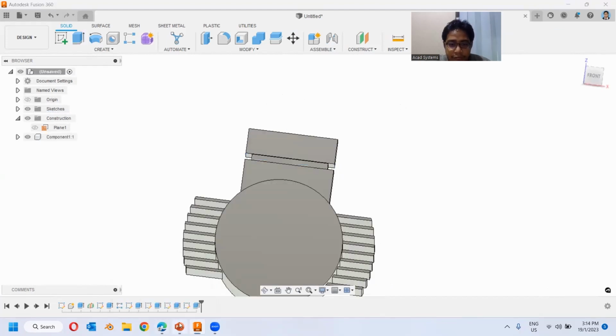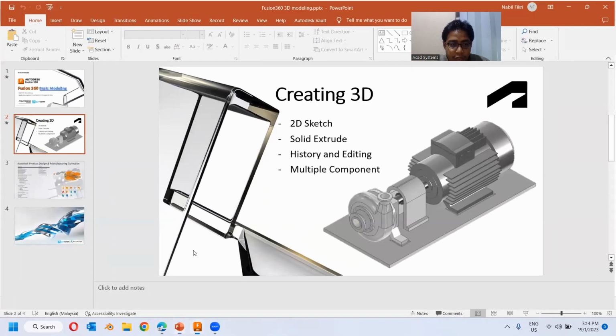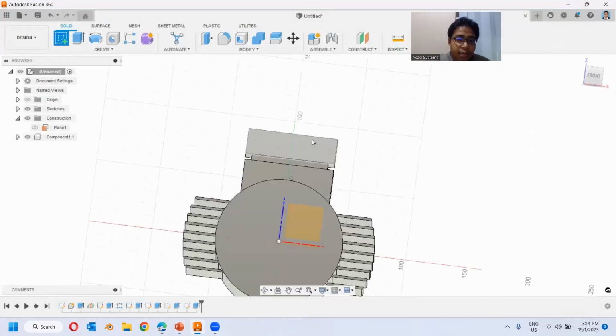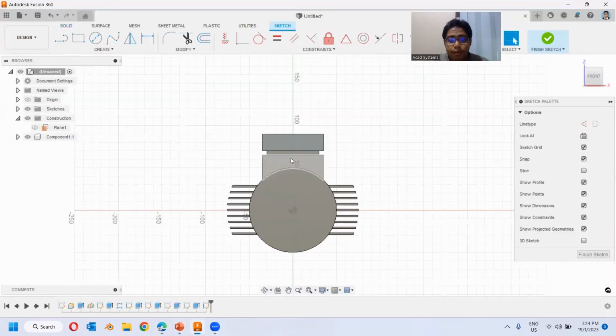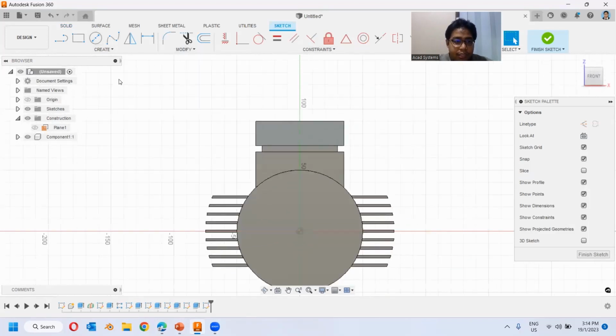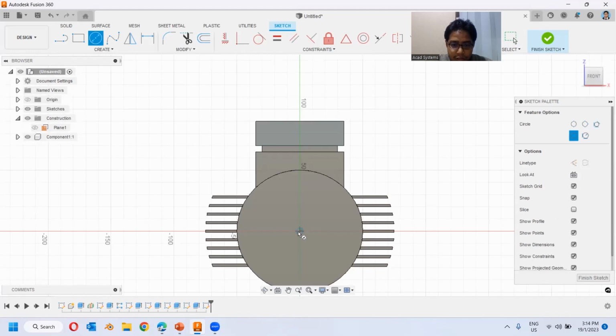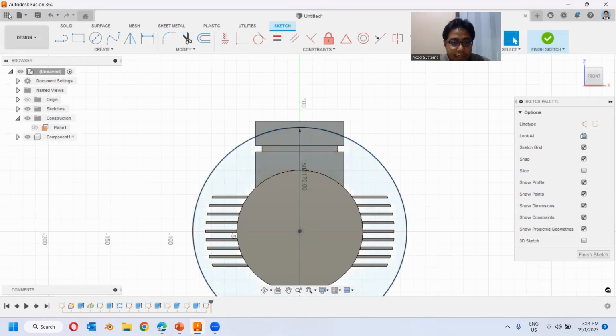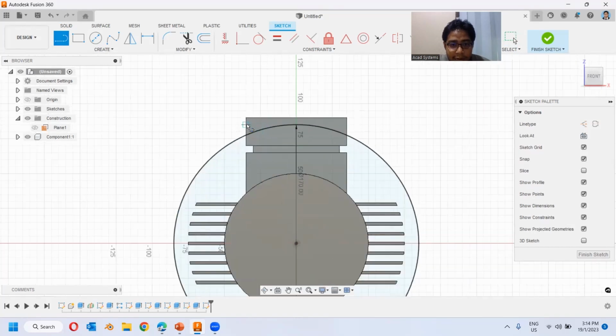And it should have a curve up over here. So I'm going to create a sketch at the front over here, and then I can select some sketch, and I can use it as a cutting section. For this case, I'm just going to draw some circles at the top over here, let's say around 170. And then there are some lines right over here. Right.